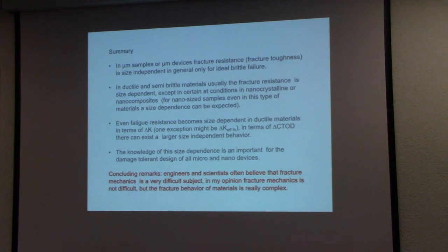Yes, the fracture process zone must be small compared to the K-dominated zone, or at least it must be small compared to the Hutchinson, Rice, and Rosengren field. And this is only the case for ultra strong or very strong material, plastically strong material. For weak or for standard structural material, that's usually not the case.